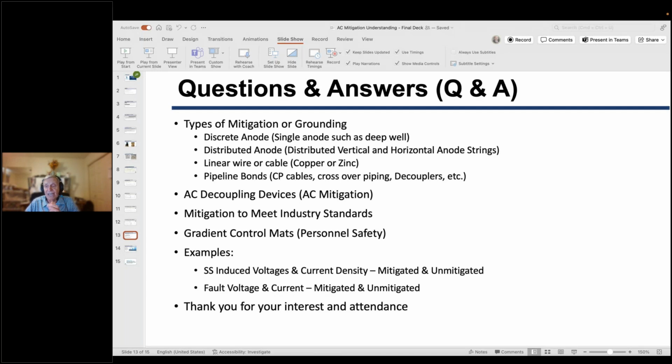And then also zinc has a tendency to passivate. So if it's not used as an anode, and that's what it's supposed to be, because it has electrochemical potential to steel, of 1.1. So keep that in mind with zinc. I would always use the decoupler, whether it's zinc, copper, whatever material you're using, just to keep it separate and not have a premature failure or anything like that.